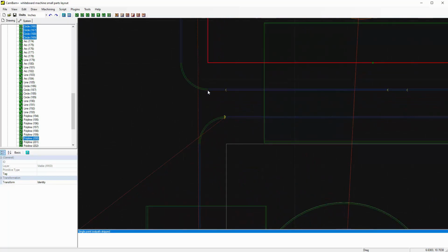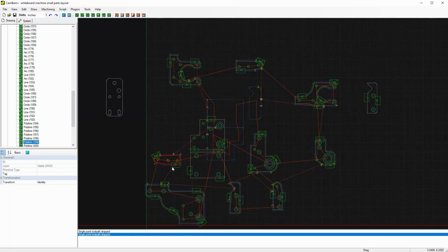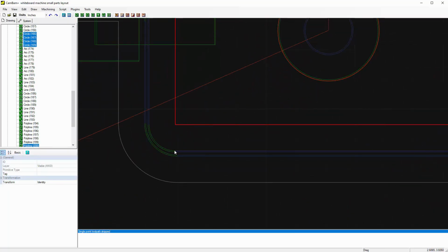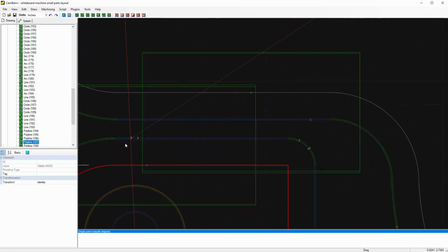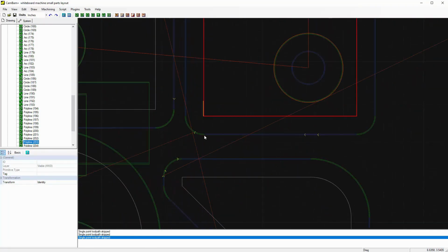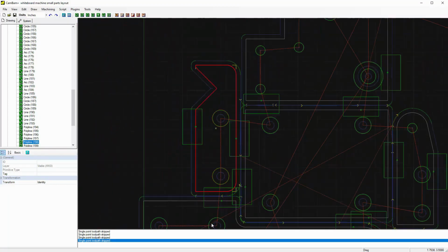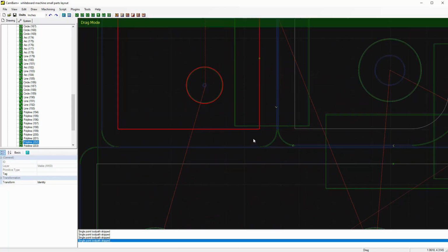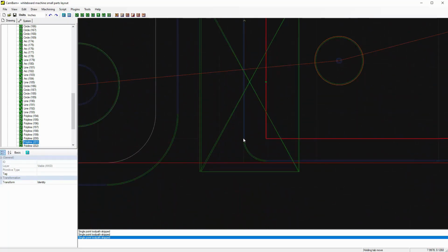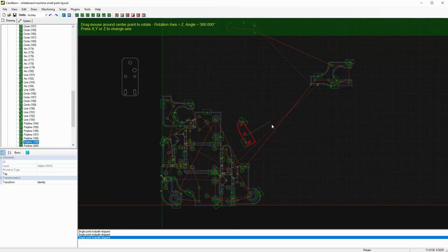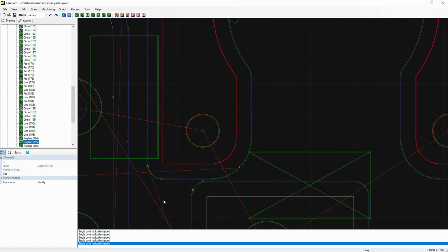The green geometry represents curved movements, and the blue geometry represents straight movements. The green and blue lines show the center line of the toolpath. So if the 2 center lines nearly touch, the end mill will move inside the neighboring operation. I find this to be one of the more important aspects of part location, as the end mill will need to be passing through less fresh material, which will lengthen the life of the tool. End mills are not cheap, so I spend the time to do this on every job. When a part is moved, the toolpath geometry is left behind, so I press Ctrl T often to generate toolpaths.